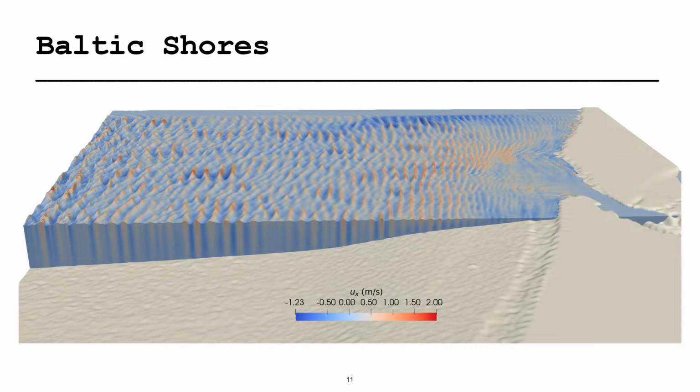There are many interesting details here you can see, not all relevant to the sediment transport, but if you look at this group of waves, that reminds me of how the freak wave would take place. The freak waves can take place in offshore area, in coastal area. It does not need to be like 30-meter tall waves, but it just needs to be much higher than the surrounding neighboring waves. In this case, the definition basically is if you have a wave height over twice that of the neighboring significant wave height, then you have a freak wave. And this pattern really reminds me of the freak wave pattern. I don't know what it is, but due to this bottom bathymetry variations and wave direction, you could actually have locally focused waves. That's very interesting to observe in the simulation.